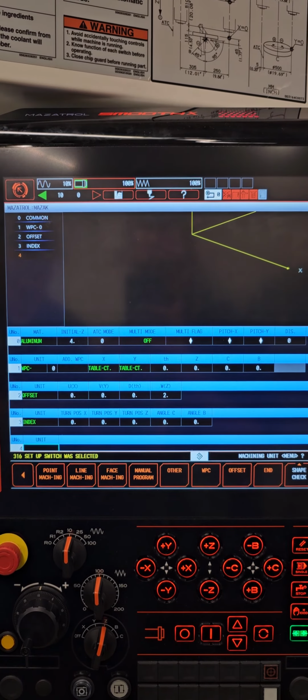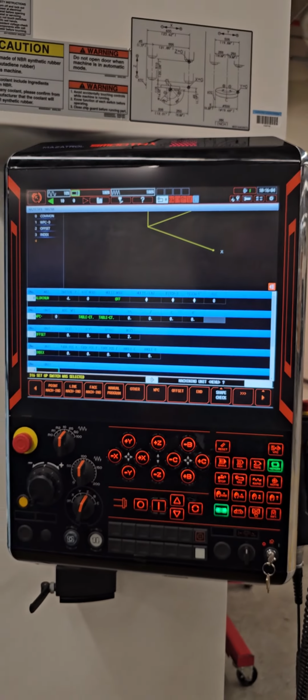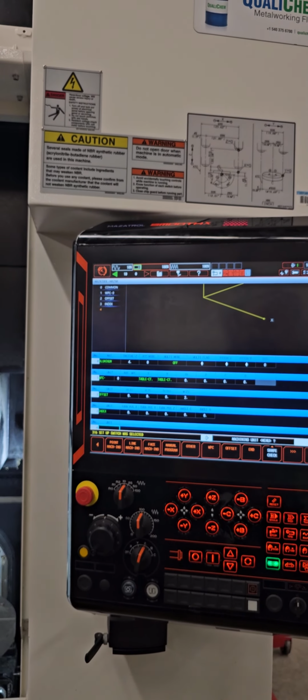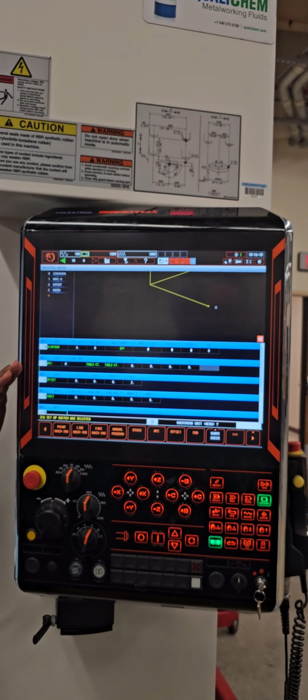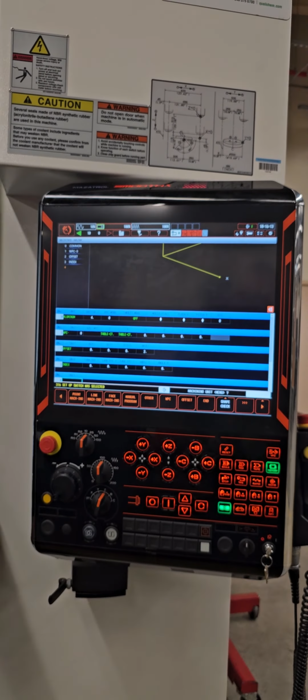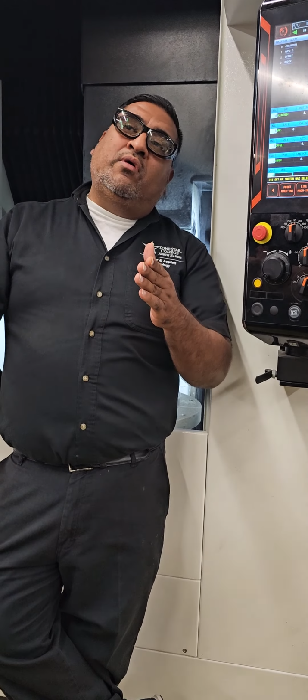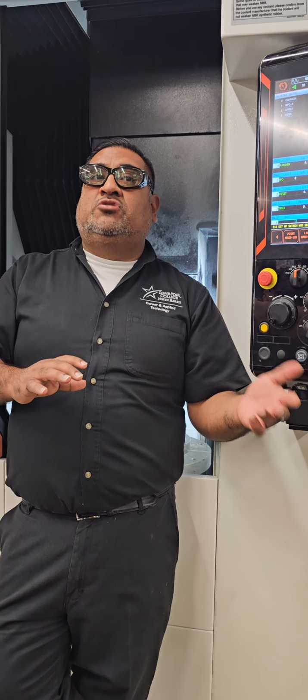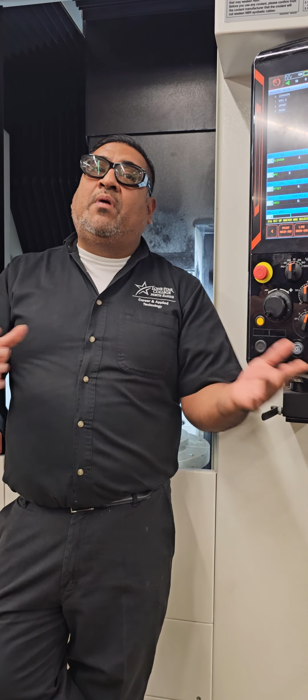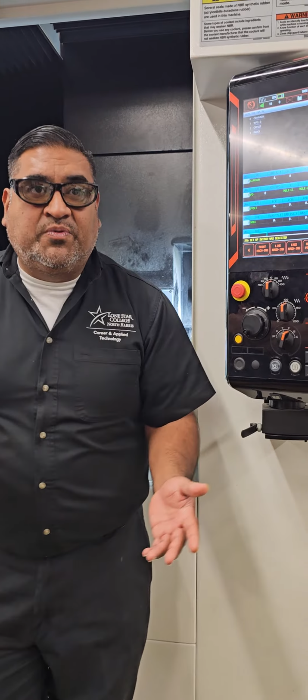All right, so we're going to have 5 lines. I lied to you guys. Every time you make a program in Mazak and Mazatrol, it never recognizes it under the actual program page unless you put an end line on there, right? So you need to tell it, hey, here's where it ends, and there's no more. If you don't do that, it's kind of like it's in an active changing status, so it hasn't completed it, so it's not going to pop up. Does that make sense? M30. Yeah, so you have to put an end on it.